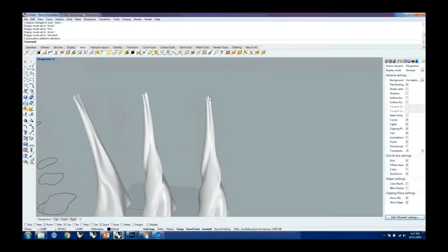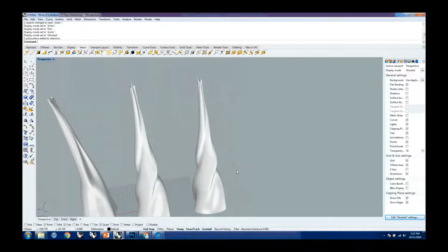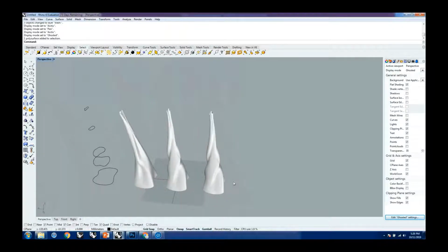So first thing that we're going to do is see where the floors are going to be. In that process, we will also take the boundary curves for all of these floors. So to do that, we're just going to use the contour command, which will help us in taking out all these curves at regular intervals.